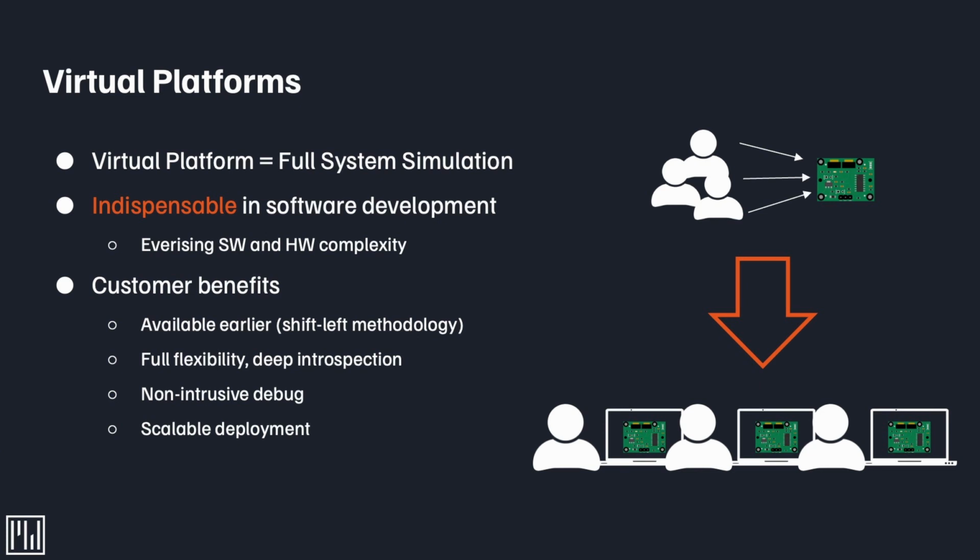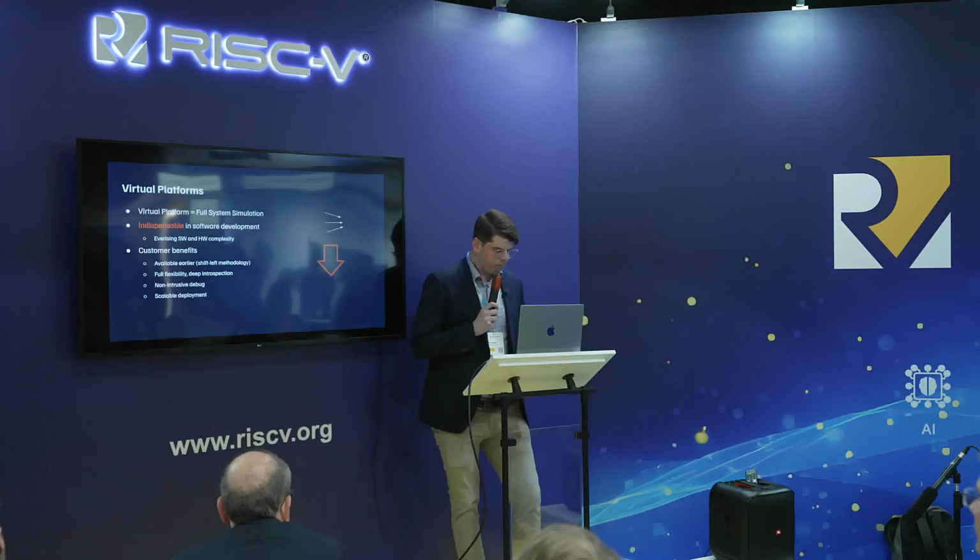Also, they are a piece of software, so they are very flexible and allow very deep introspection in the simulator. You can press pause anytime and look at exactly what the system is doing. They also allow for non-intrusive debug, so you can attach debuggers to it and check what the system is doing. And last but not least, and that is the issue I mentioned before, they are extremely scalable. If you have a simulator of your system, you can easily copy it 1,000 times, 10,000 times, and run it in the cloud to parallelize all your testing.